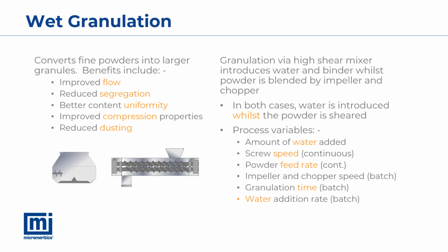Granulation is favored in many powder processing environments for its value in improving the handling properties of otherwise hard-to-process powders. Further to this, by reducing segregation and thus improving the uniformity of final products, it can have a beneficial effect on ultimate product quality, as well as preserving safety and cleanliness in process environments by reducing dusting.